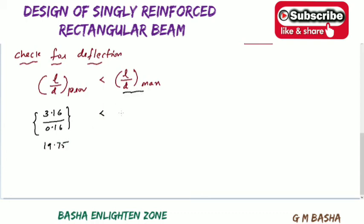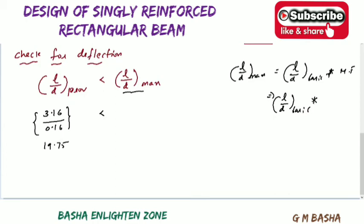What is this L by d maximum? L by d maximum will be equal to L by d basic into its modification factor. Okay. In the modification factors, what are the things you will get? L by d basic into kt, kc, kf: modification factors for tension reinforcement, compression and flanges. Here we are finding only tension reinforcement because it is a singly reinforced beam.